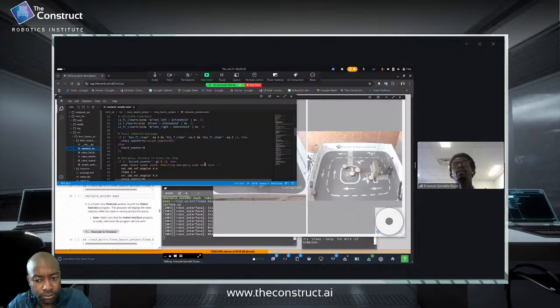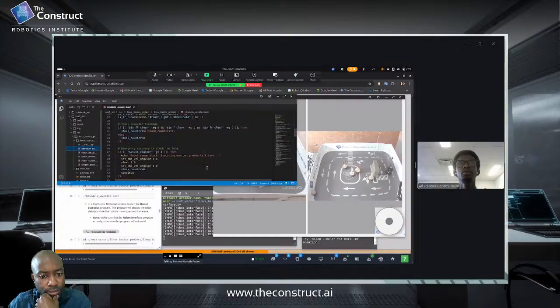The ideal thing to do is, I would say, making the robot really make the decision and make the turn, because that's what's ideal when you're working with, let me not call it an autonomous robot for now. There is no way it's going to do that. So basically, we have these three things. It gets the clearance, and it tracks repeated blockage. Now, if it's blocked for too long, then it's going to launch the emergency recovery. But there is no time threshold that it has to reach and then stop the robot completely.